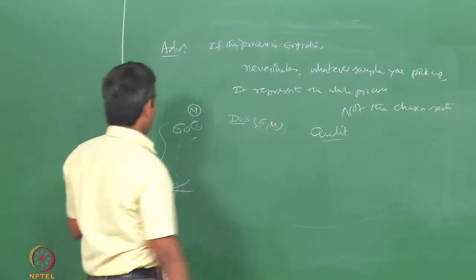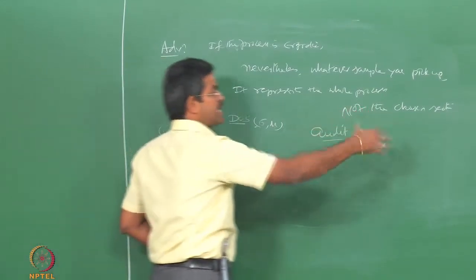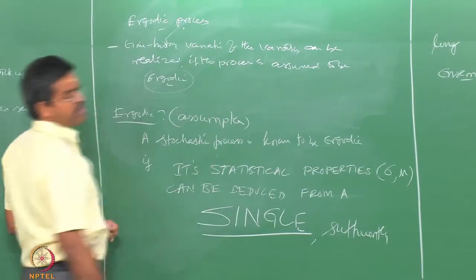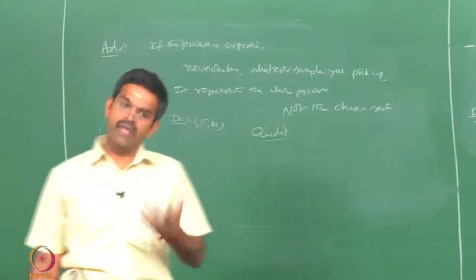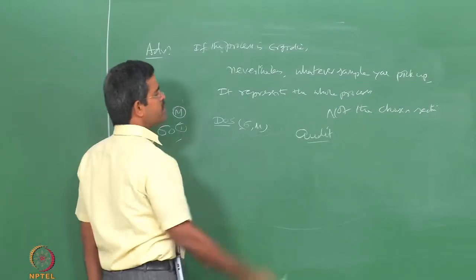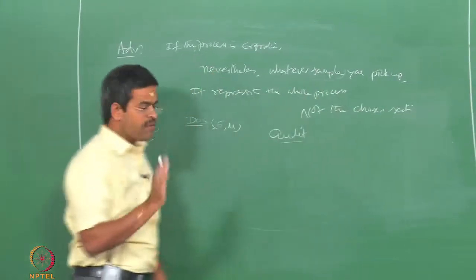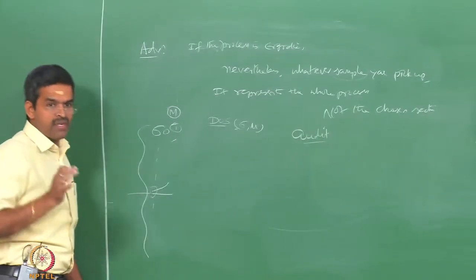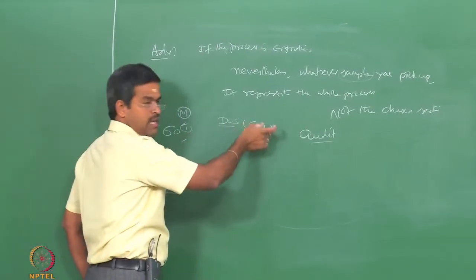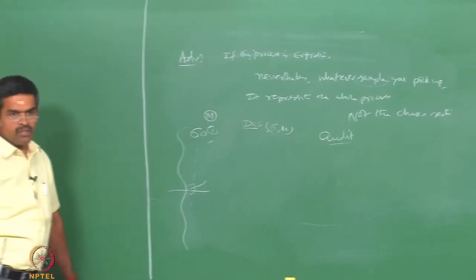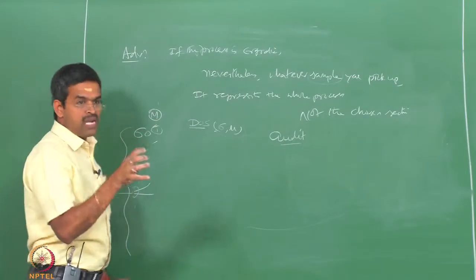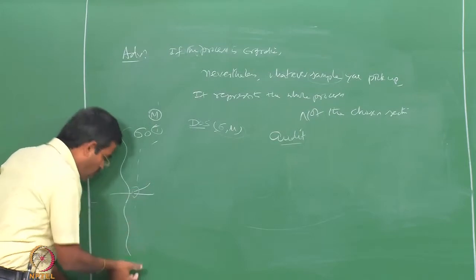Okay? So, getting an ergodic process is generally an assumption, but by luck, in reality, sea surface elevation is assumed to remain ergodic. Okay. So, the advantage is that we need not bother about the variation, we pick up any one sample. It does not matter which sample you pick up, because by the ergodic definition any sample in that scheme should represent the same mean and standard deviation as that of the whole process. Okay. So, it does not matter what sample you pick up, but it is very clear the sample does not give a self understanding within the section, but it is a representative value of the whole process.